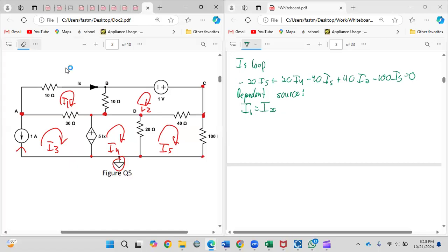Assuming we do a nodal, some cool thing is if you have a current going in this direction. You have a node here and a node after, so say there's VA and there's VB. If current is going in this direction, the arrow will be going from a plus to a minus. Remember, the current going through here will be a voltage drop, because current flows from a high potential to a low potential.